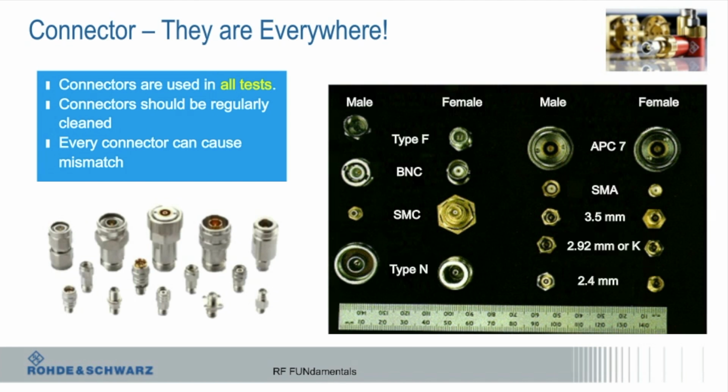Question? Yes. You're saying that the thread pitch on all, like the SMA, the 3.5, it's the same exact thread? No. What I'm saying is these two will thread, and this one and the 1.85 will thread. Did you say the SMA will also thread? SMA technically will, but again, this isn't a precision connector. So it does happen where you plug this into this and it damages it. More often than not, the center pin, because it's not a precisely toleranced center pin, might be offset and not go in correctly and then bend the pin.